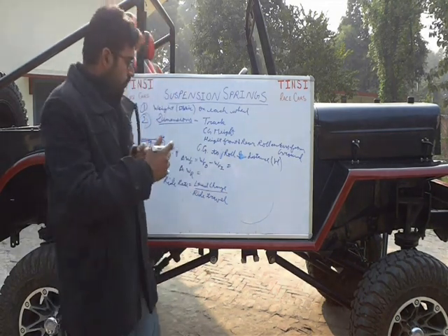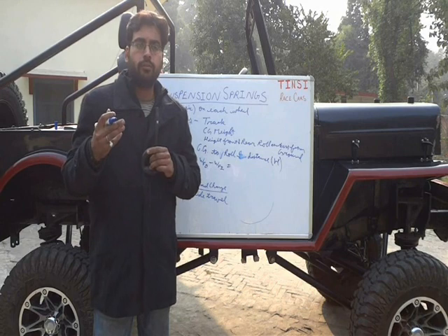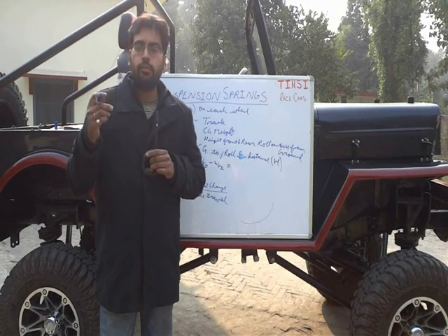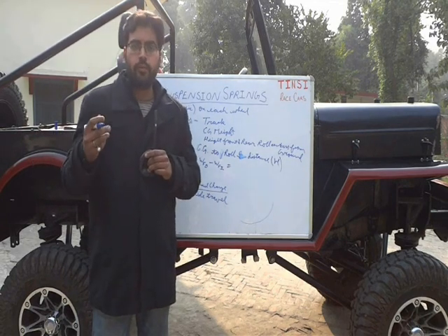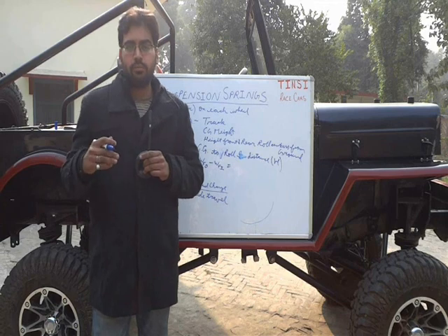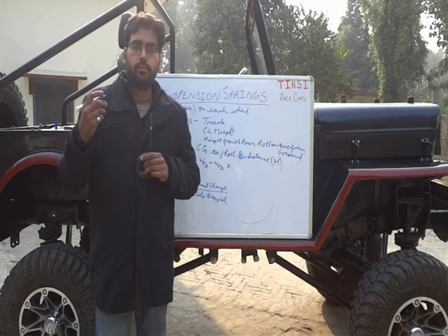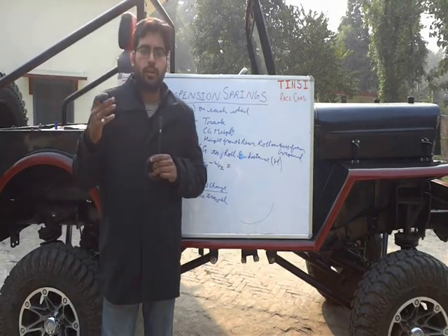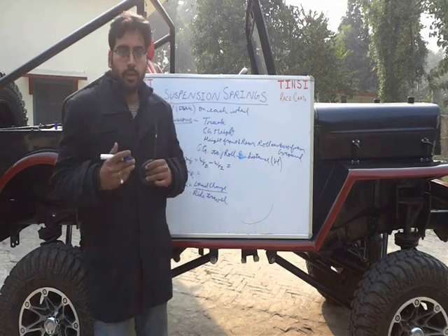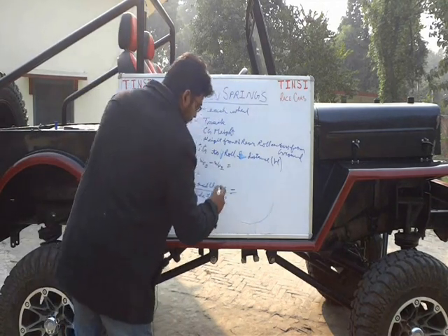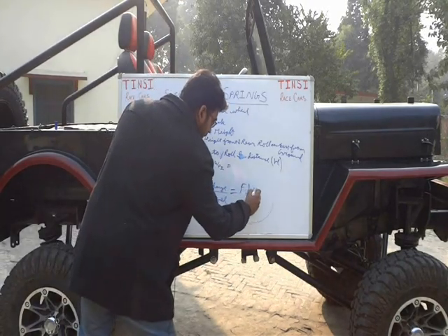You want to attain this amount of load change within your specified travel, or within your 1 inch of travel, and you want to leave around 0.5 to 0.25 inches for the bumps and the travel of the suspension because of load transfer from longitudinal accelerations or braking. So we need to cater for all that. So we go here for the ride rate. You can get your ride rates from here, both front and rear.